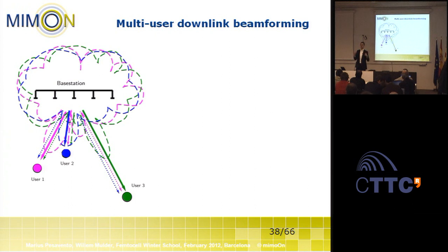There are also some iterative algorithms that can be designed here, where we can again use uplink-downlink duality. So instead of designing the downlink beamformers, we can design uplink beamformers, and there's a fixed point iteration algorithm that can be used, which converges in a reasonable time. But it's not based on the water filling principle. Okay.